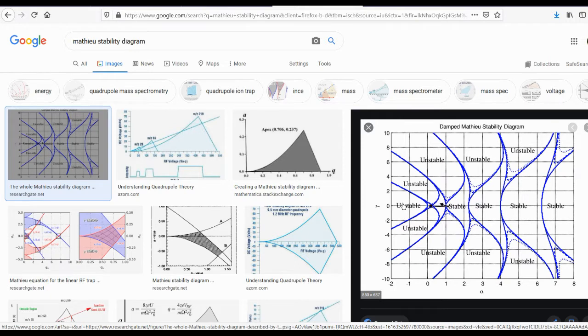You can see they are all unstable here in these regions, but there are actually narrow regions of stability, and over here there are fat regions of stability with narrow regions of instability. This is damped, so there are these dashed lines, but the solid line corresponds to the undamped case. And then over here this point is 1/4, which you should be able to connect with, because the natural frequency corresponding to a spring stiffness of 1/4 is half, and that frequency is half of the forcing period.